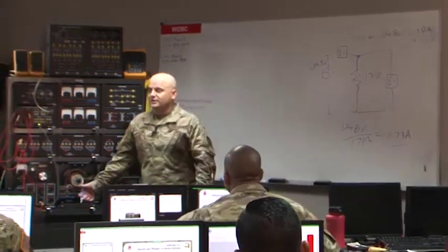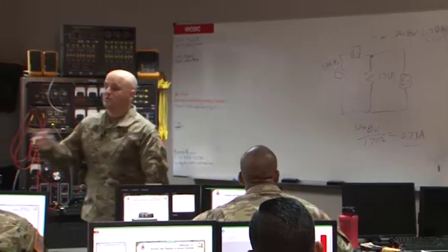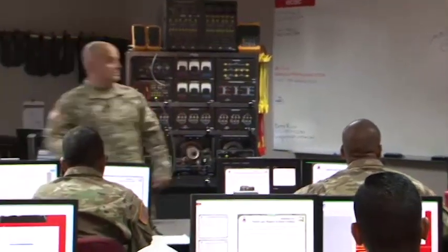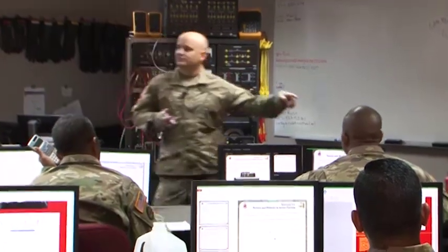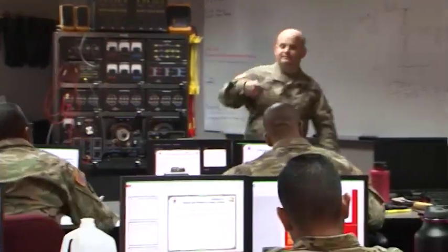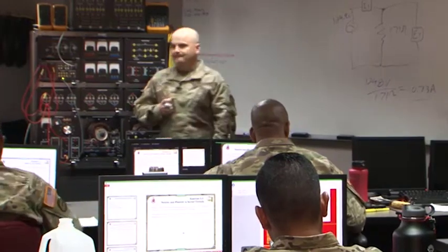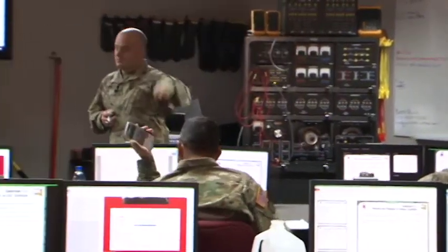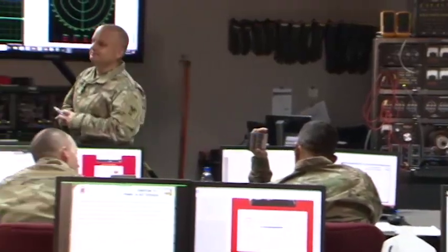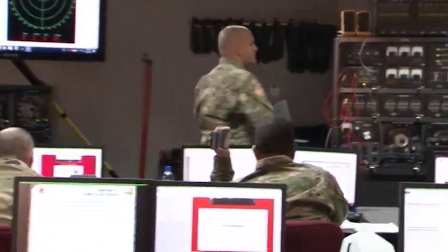Or you could have used what? You just calculated the current, so you could have done I squared R. You could have done 0.73 amp squared times 171 ohms. Does that come out to be the same? 91? Check. Tell me. Yes. Is it the same? Yes. Cool. So we could have done either one, right? All right, so that's the apparent power.